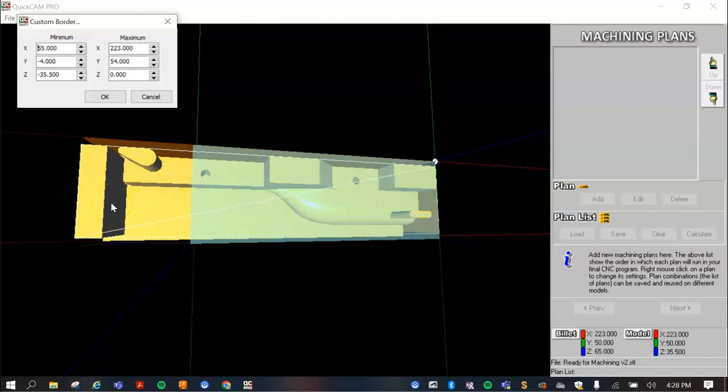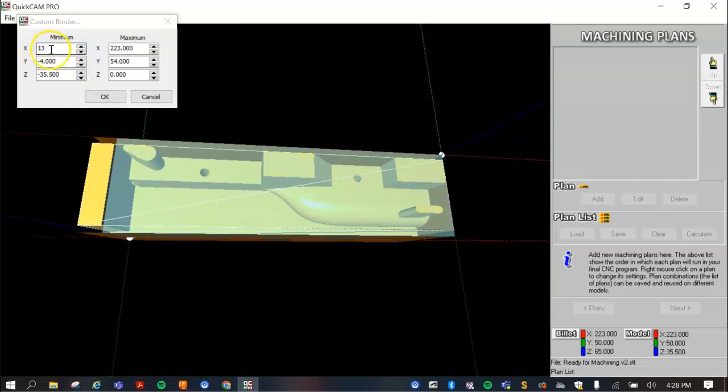The only thing that you need to be sure of is that you've got at least about 4 millimeters around that part. So if that's your front wing, for example, you would need to make sure there's about 4 millimeters there so the cutter can go through and actually cut that off. But for us, like I said, we're going to leave this one at 13 millimeters, just so it doesn't go through and cut our fixture. So for most of you, you'll probably use 13, but for some students who have smaller cars, obviously you can bring that further across.